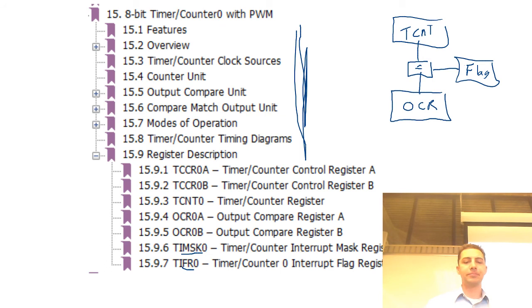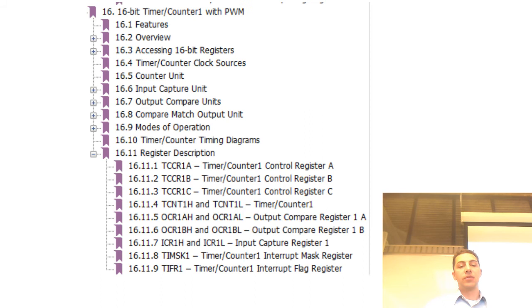Great dad joke. Yeah, mask is responsible for telling which interrupts are going to fire. Flag tells you which interrupts have actually fired. Then we've typically got some amount of control registers, and then here are my timer registers. I've got a free running counter, 2 channels of compare. Timer 1. Let's look at timer 1. Mask register, flag register. What does the mask register do? Someone else?